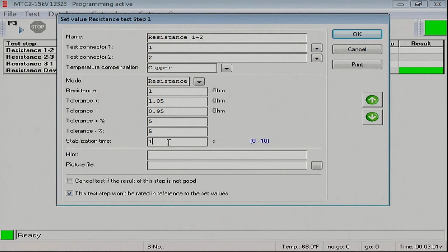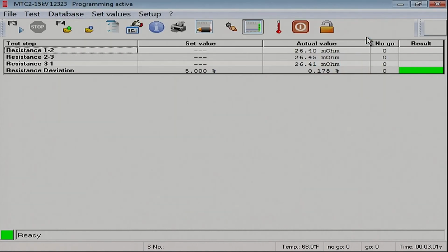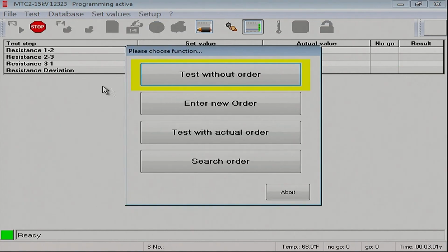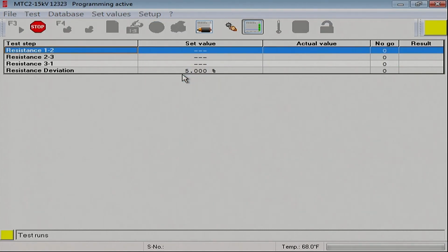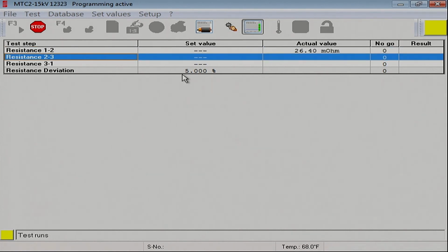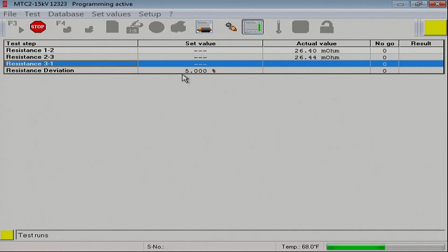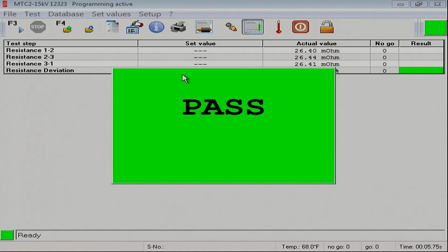That will give the system plenty of time to stabilize in a very good and accurate reading. Now I'll do that to the other 3 steps. And there we go. So now it'll run a little slower, but we're guaranteed that this test plan will work for any stator that we come up to, even very high inductance stators.